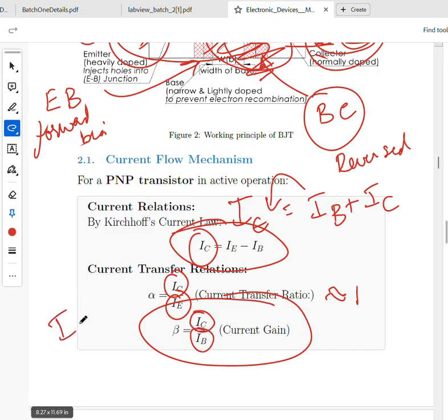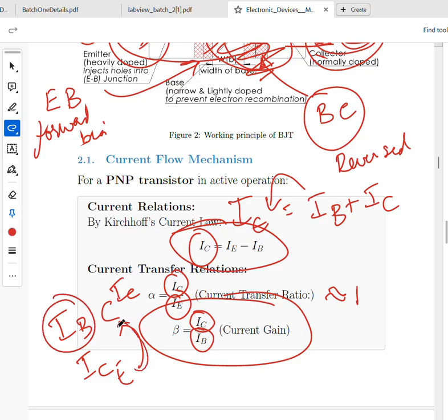Current gain is telling how much change in collector current is happening from the change in base current. We've talked about how varying base current even a little bit changes how much current passes from the emitter to the collector, correct? That is the IC current. So this small change is determining how much current transfers from E to C. We measure this as a ratio, the current gain.